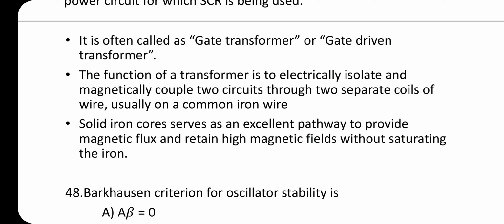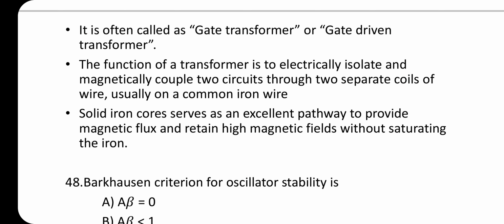The function of a transformer is to electrically isolate and magnetically couple two circuits through separate coils of wire, usually on a common iron core. Solid iron core serves as an excellent pathway to provide magnetic flux and retain high magnetic fields without saturating the iron.